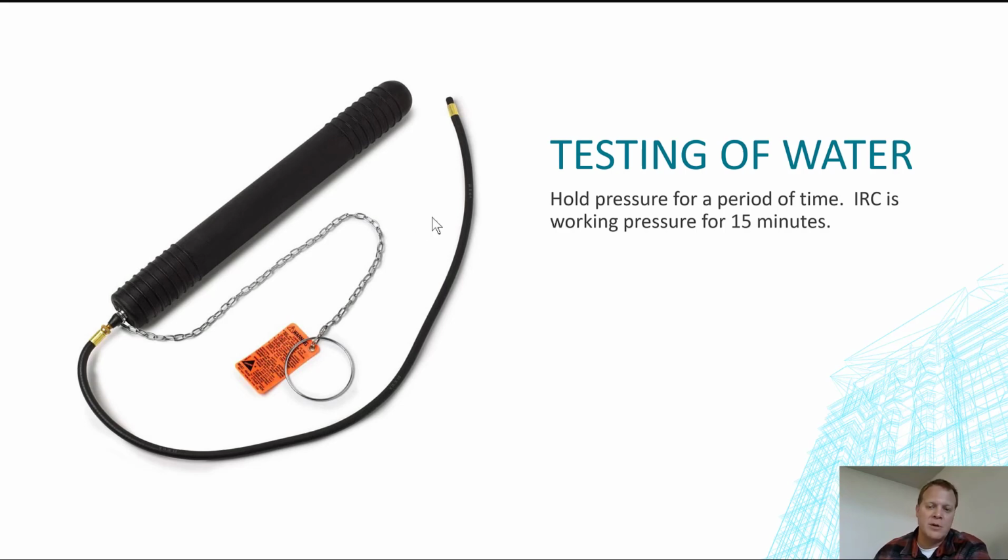Usually you just cap it and put a little, well, you'd still use something like that in the end, but basically fill up the pipe with water or with air and pressure test it for a period of time. Usually, like the IRC, I even put it in here. IRC is 15 minutes of working pressure. So if we had that pressure reducing valve set at 70 psi, then we pump this thing up to 70 psi, wait 15 minutes, and make sure that it held at that pressure for 15 minutes. It didn't drop down.